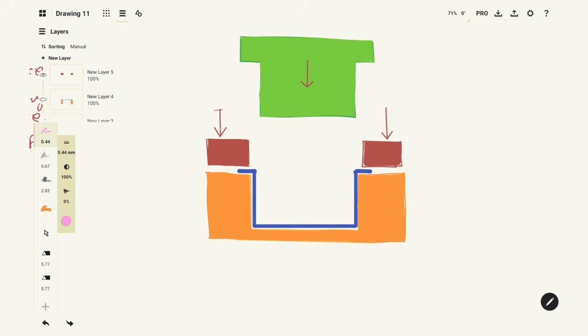Even if we want to manually collect the part from the die, it won't be easy because it sits inside the die. So one solution is to use an internal ejector within the die to lift the product and then slide it out, or take it out. But it has a major drawback. It could damage the finished part because the sheet thickness is only 1.2 mm, especially if the ejector force is uneven. So a better approach, instead of ejecting the part from inside the die, is to flip the setup upside down.